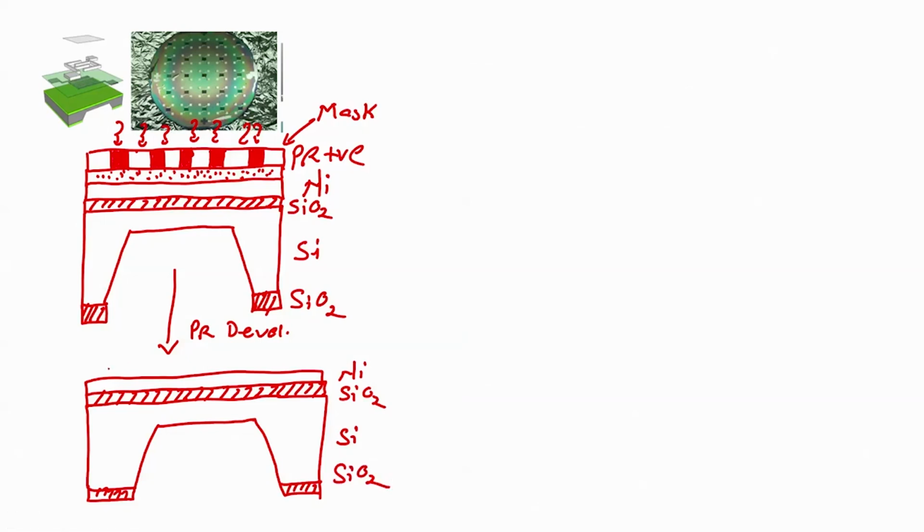then photoresist will stay in this area. Why only this area? Because we are using positive photoresist and the area which is not exposed, right, will be stronger. So, we get this particular pattern. Next step, after developing the photoresist, would be hard baking.